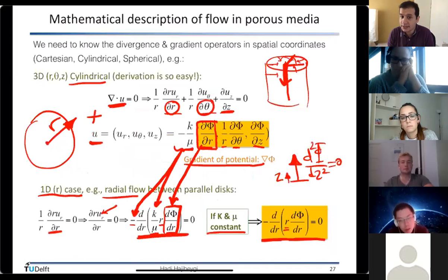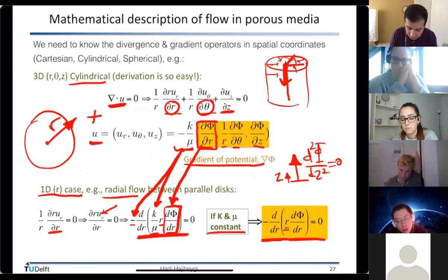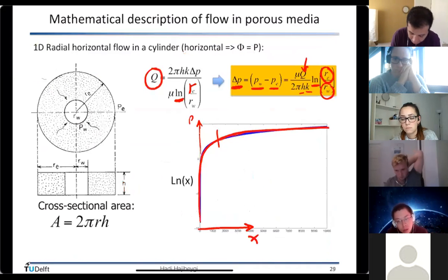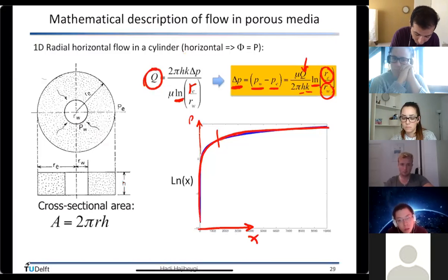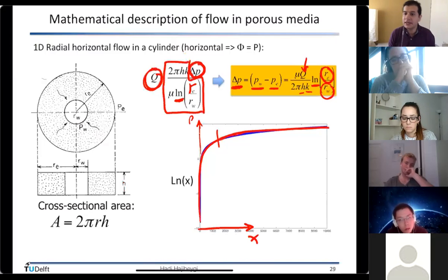And that's the steady state well flow rate that Peaceman studied many, many years ago, and he found the well productivity index based on exactly Darcy's law around the well at a steady state and the continuity equation, which is divergence of U. What I like from this whole story is that the thing you did in the simulation course, to relate the source term of the well to be a function of your delta P, is actually coming from Darcy's law and incompressible flow science.